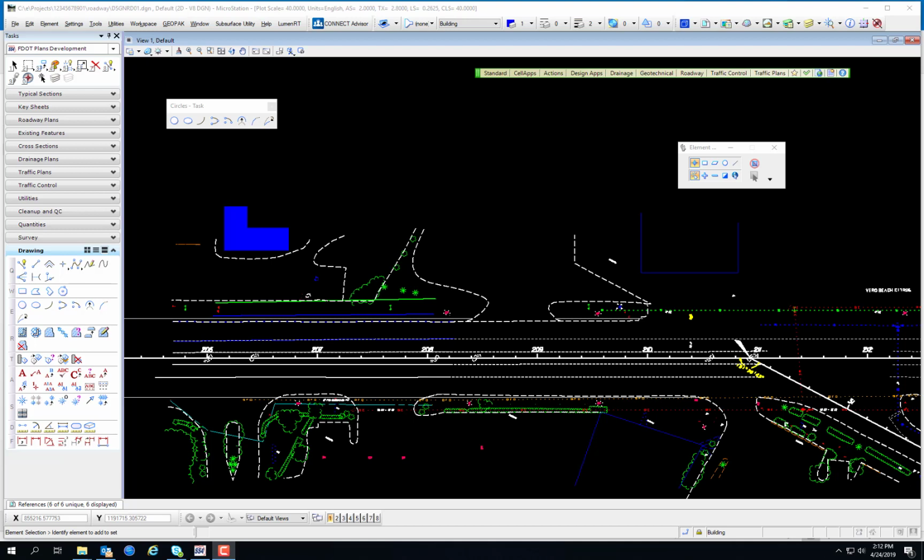Locks are drawing assistance tools that can be used to help produce drawings more effectively. There are settings that allow more control of the actions of various tools. These locks, to different degrees, control how MicroStation controls the cursor, data point accuracy, or groups of elements.